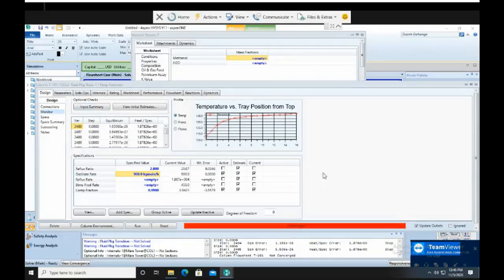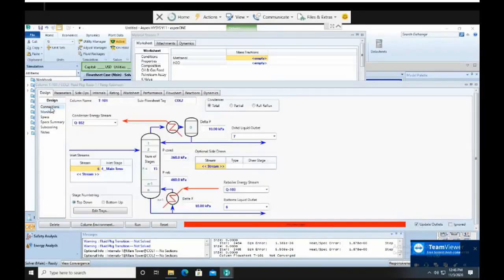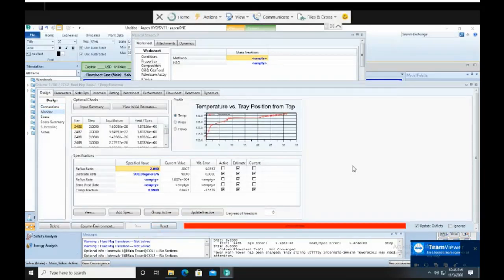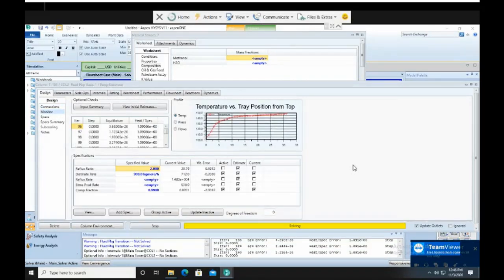Okay, now we know that we can actually change our stages. Let's change this to 30. Enter, you go to monitor, you run. Tengok, dia improve tak? Okay, now the current value is at 0.9701. We want to achieve 0.99 of methanol at the top. So this is still struggling. They're still struggling calculating it.